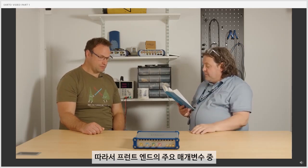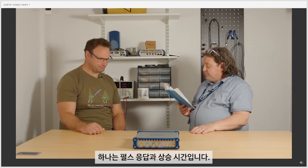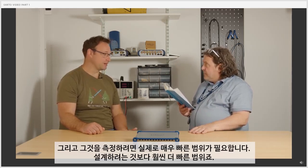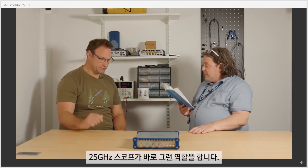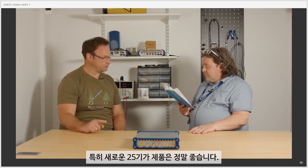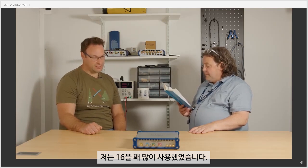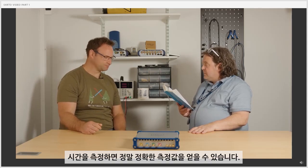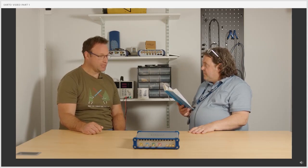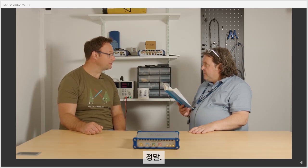So one of the key parameters of our front ends is pulse response and rise time. And to measure that, you really need a very fast scope, much faster than what you're trying to design. And that's where this 25 gigahertz scope comes in. The new 25 gig one particularly is really good. I used to use the 16 quite a lot. So when you're using this to measure rise times that are hundreds of picoseconds, then it gives you a really accurate measurement. And we can look at overshoot and the pulse response to see where we're at really.